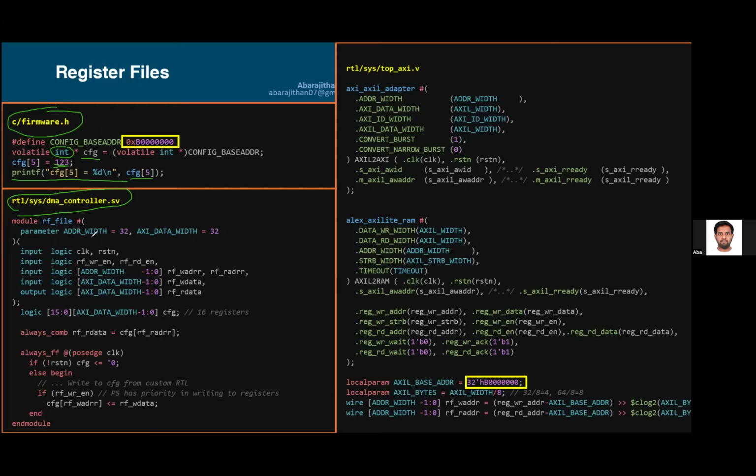So what we do is we define these ports. You have the clock port, you have the reset-n port, and then you have an address width, and you have the write address and the read address. Okay. So these are the read address and write address. And also you have this write data and read data. These are input ports, and this is an output port, so the read data is an output port.